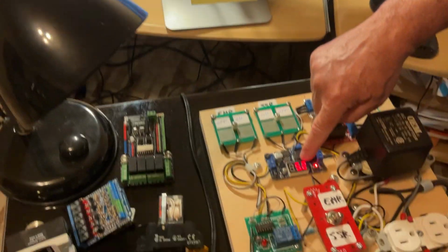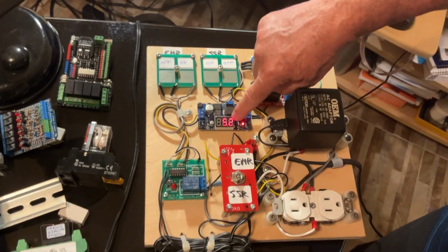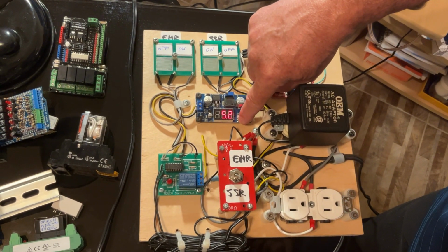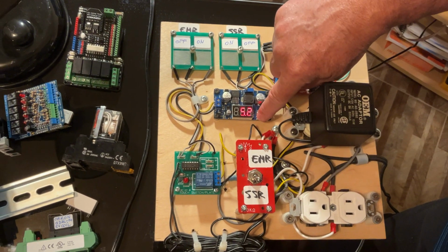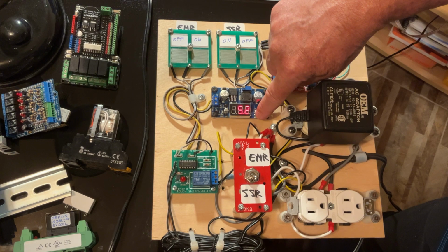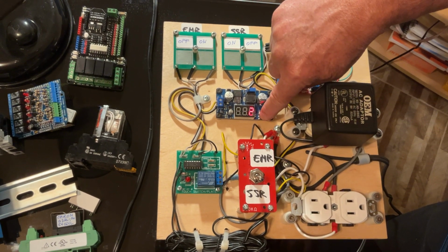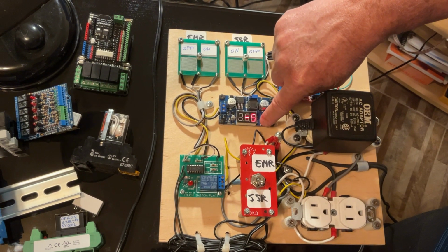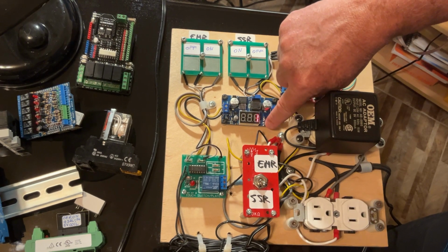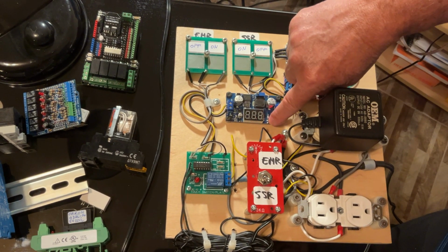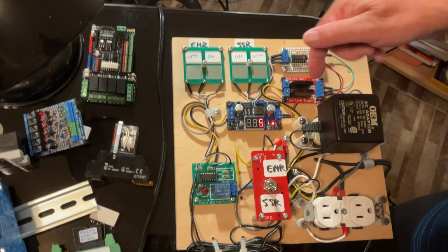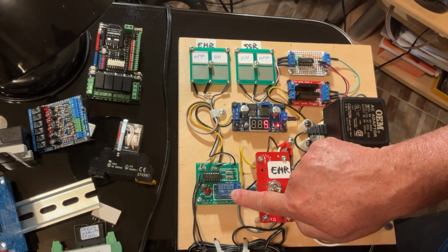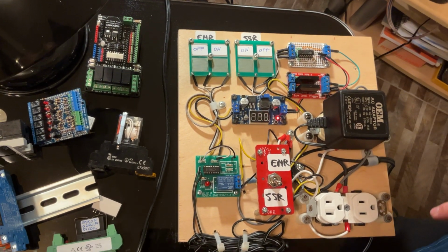5 volts, this is why I read here on the DC to DC converter 5 volts. You take it with some tolerance, now it's 5.2, it's no big deal. If I press the little button here, this button gives me information, okay? However, the voltage for me is 5 volts for the solid state relays, and it's going to be about 12 volts for the electromagnetic. Now, let's use it.